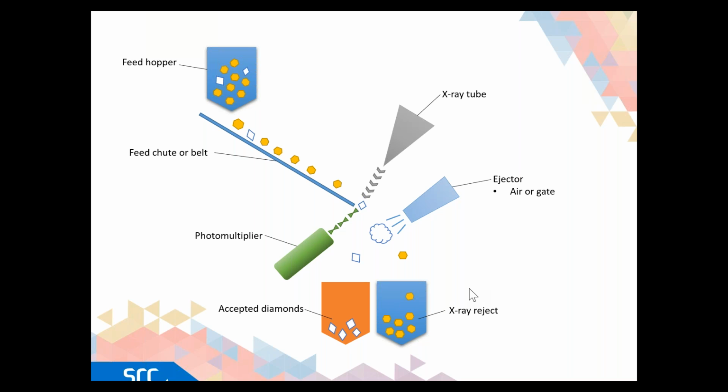or for coarse rejects. These can also come in several different configurations with a variety of feed presentations and ejection mechanisms. The residence time, the amount of time the particle is exposed to the energy source, can also vary depending on the equipment manufacturer. So that can also add to the need for understanding of the properties of the stones. Your yields can also be affected by the threshold of the X-ray sensing, so you really have to try to find a balance.